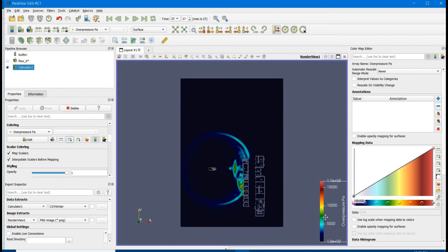You can see at this stage you've got a little bit of green, which is just under 0.05 bar, but this is late in the piece. So if we go to, say, 20, it might get a higher pressure. Yes, in fact we've got 0.15 bar at the edge of this. So any windows at this stage would be broken. If the building is not fortified, you'll have major structural damage. You could even have collapse. So it is quite a large overpressure that's sitting there.